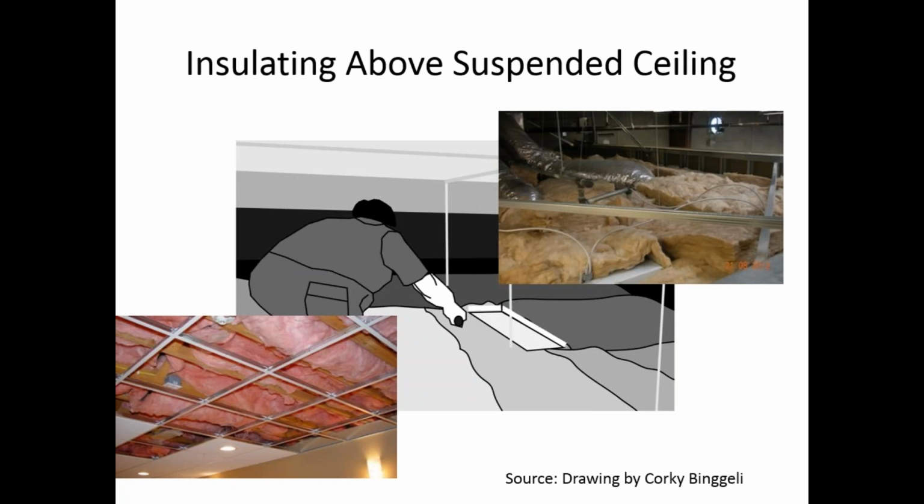So here I have insulating above a suspended ceiling. Here we have our different type of HVAC and ductwork just going in your suspended ceiling. You will not see this a lot. I've worked at a number of open offices and they don't go this extra step. This will really help to stop some of the sound problems between an office and possibly a break room or an office in an assembly area or conference room.